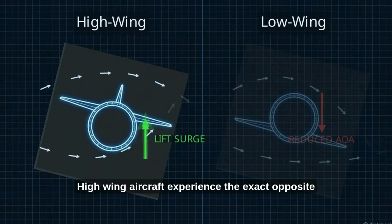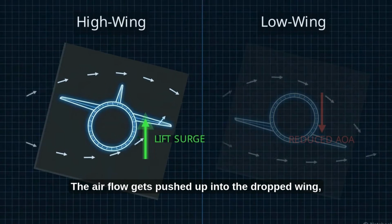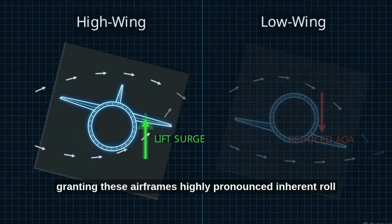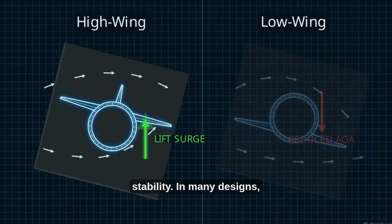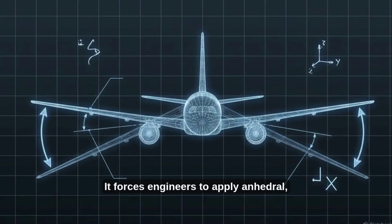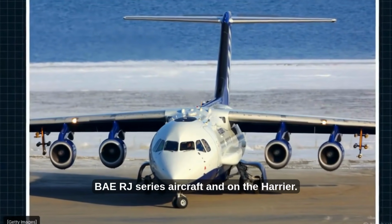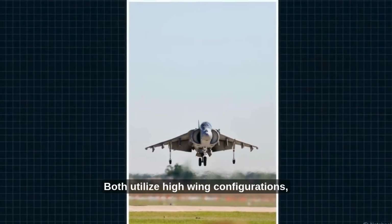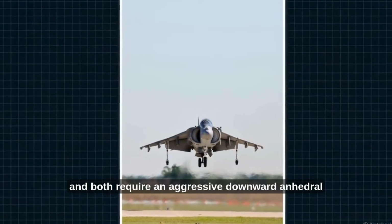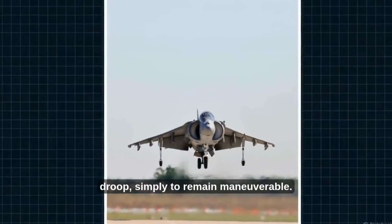High-wing aircraft experience the exact opposite crossflow effect. The airflow gets pushed up into the dropped wing, granting these airframes highly pronounced inherent roll stability. In many designs, this inherent stability is actually too strong. It forces engineers to apply anhedral, a negative dihedral angle pointing downward, just to compensate. We can see this effect clearly demonstrated on the BAE RJ series aircraft and on the Harrier. Both utilize high-wing configurations, and both require an aggressive downward anhedral droop simply to remain maneuverable.